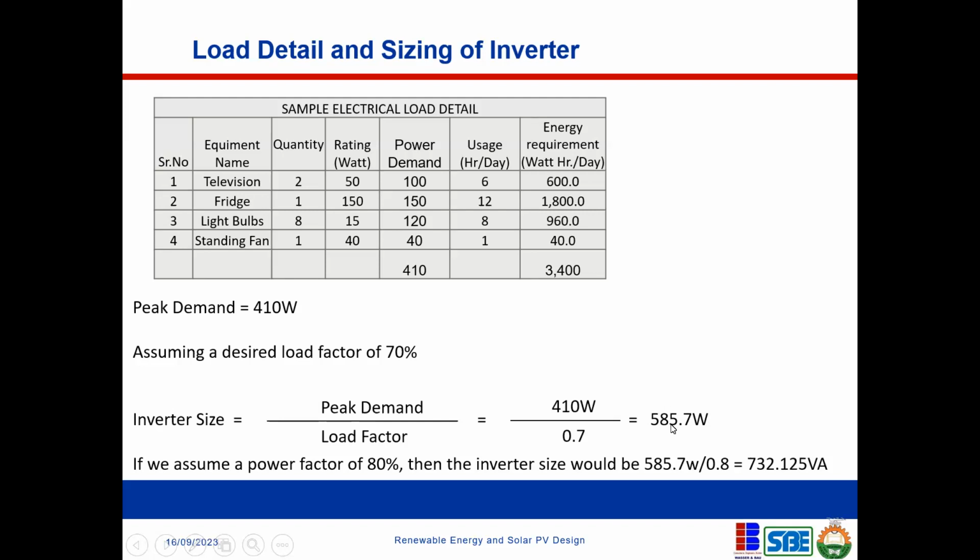And please pay attention. Some inverters are rated in kVA, some are rated in kilowatts or watts. So pay attention to the unit of your inverter. So this is the amount. If you're working with watts, as you go to the market and you see the kind of inverter that you want to buy, but it is rated in watts. Okay.